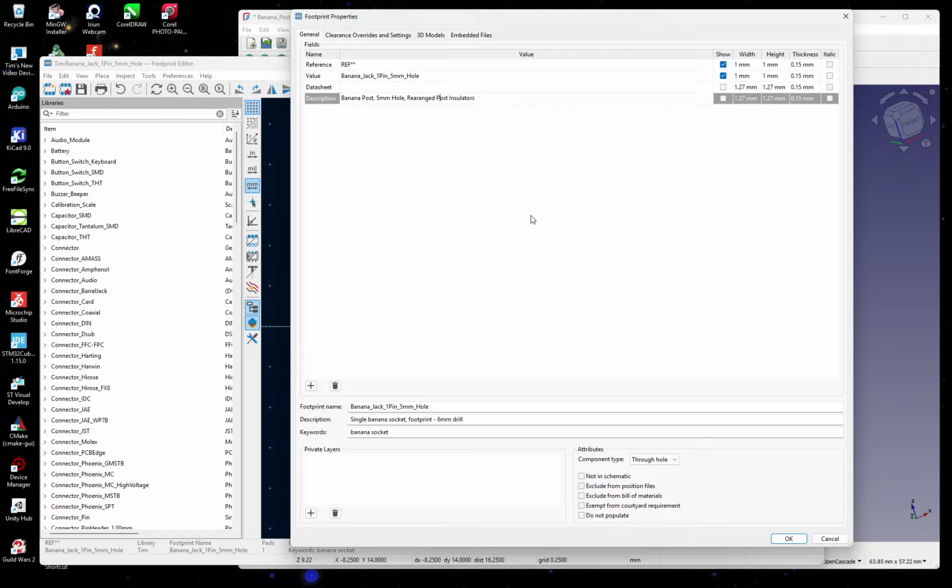Right, so yeah, you tick these if you want them to be viewed in the actual PCB, but I don't, so just leave them as that. Let's go description. Get 5mm hole, so it's not that one there, and we can put that in description. There's two descriptions, because one is actually shown on the PCB editing. It's shown in the actual thing, and the other one is the description for if you're adding descriptions.